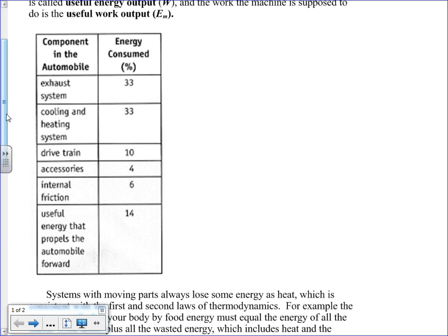On the highway, your hybrid vehicle runs mostly on the gas engine. The purpose of a hybrid vehicle is to use the electric engine to assist the gas engine under times of load. So when you are accelerating and things like that, the electric engine kicks in and assists the gas engine. When there is no assist needed, it runs on gas. So hybrid vehicles must be used efficiently under city driving conditions, stop and go traffic, not on the highway. Otherwise you're just not getting the benefit out of them.